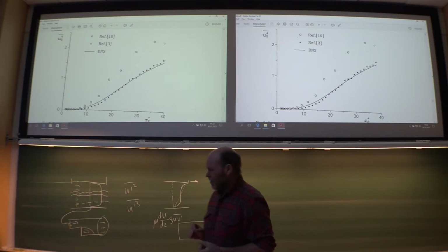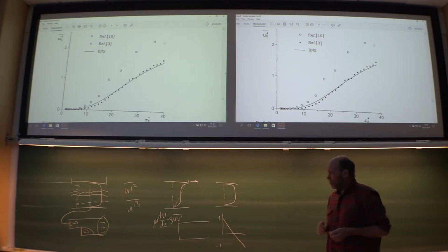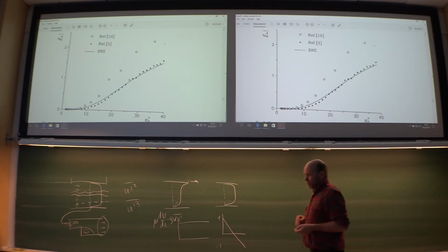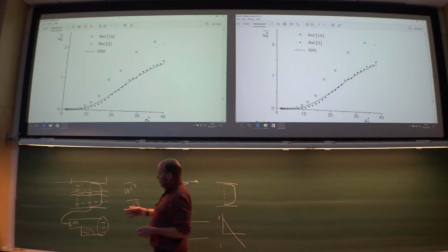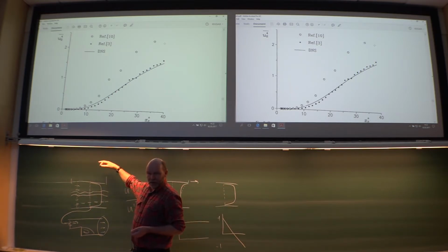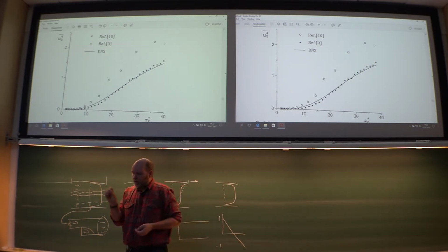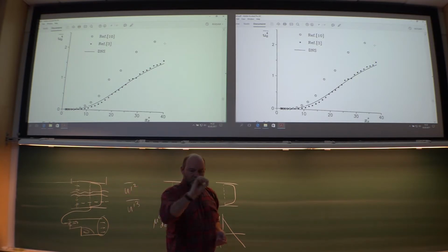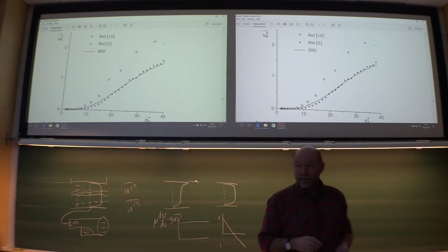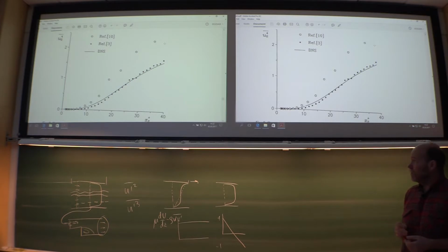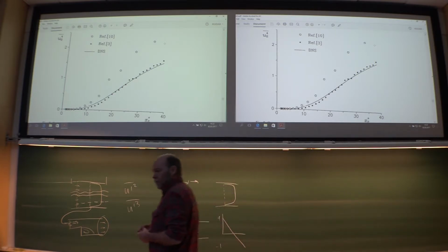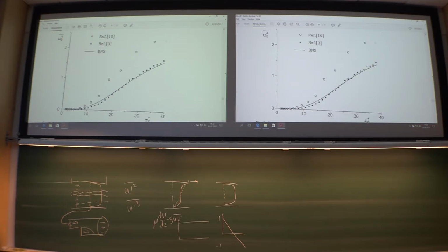You send a lot of fluid markers, particles, into the flow, then you set up three or more video cameras, and from the videos you identify each particle and trace it in space and time, and then you calculate the different quantities out of that. Very hard. I think they used just about as much CPU as I did on the DNS, just to do the calculations.